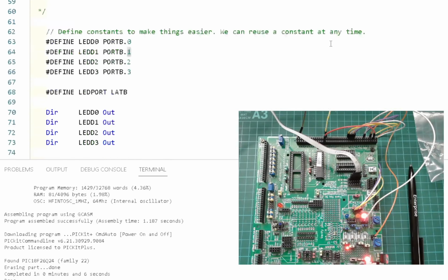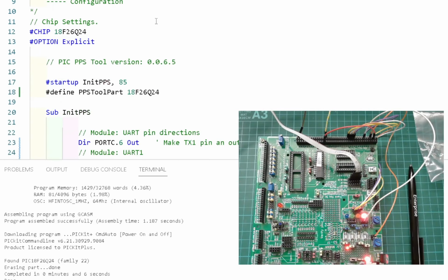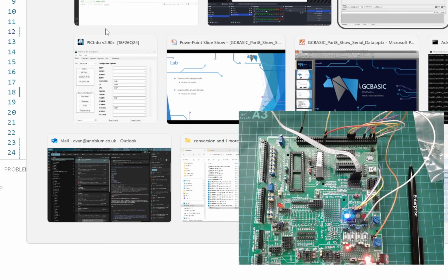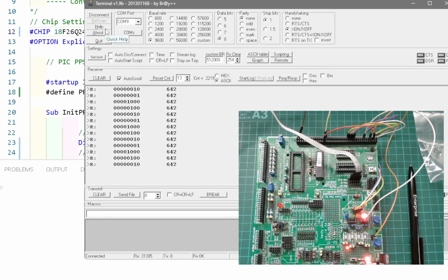We're going to pretend for one moment that we need to run our compiler at 1 megahertz because of power. Function key F5 to compile our new option, and we will see it will say on our string that it's the same chip, but it's running at 1 megahertz, and we'll see that because I'm going to disconnect it after it's compiled it.